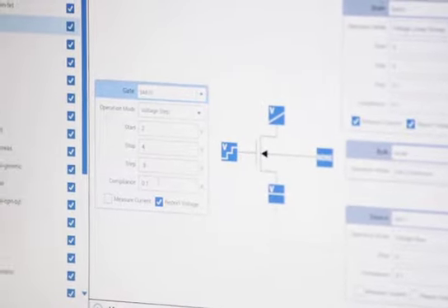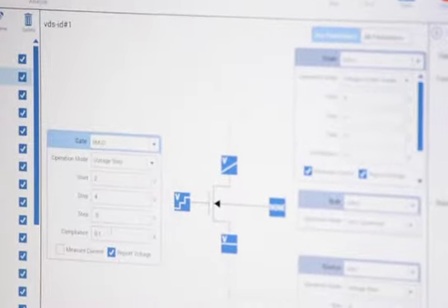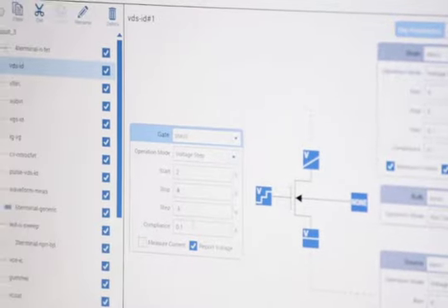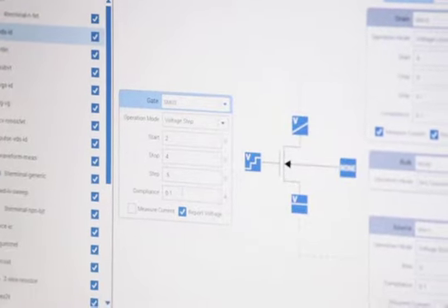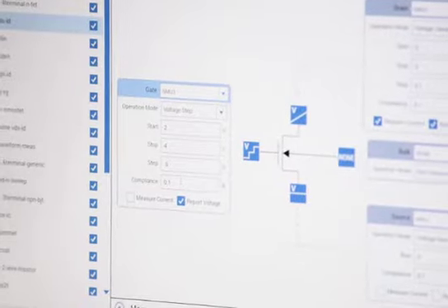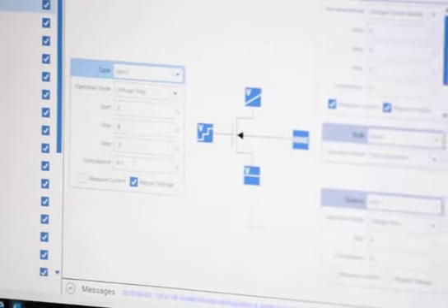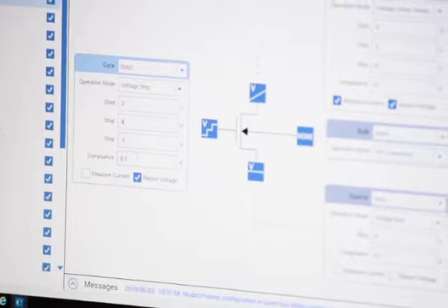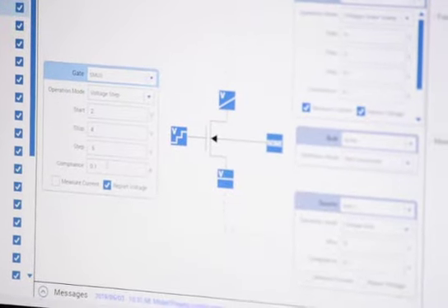Another important thing here is that every SMU has 2 A to D converters. They can measure voltage and current, time correlated at the same time. Some of the SMUs you may have, the Keithley boxes, only have 1. This has 2. So that's important if you're trying to measure power, for instance. You want your current and your voltage measurement done at the same time. On some of the other instruments, it has to do 2 sweeps, one for voltage, one for current, so you don't have any time correlation. This has time correlation, so it can measure them both at the same time.